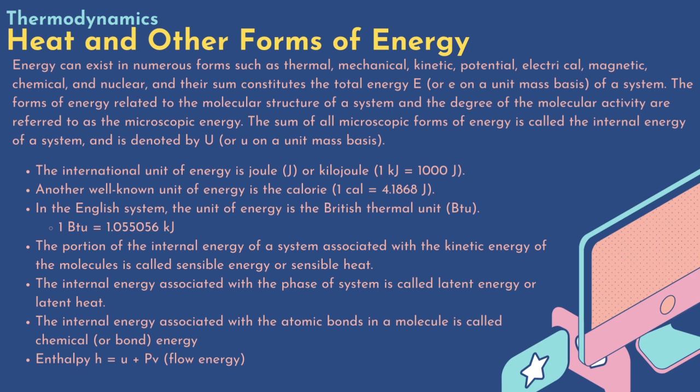In the analysis of systems that involve fluid flow, we frequently encounter a combination of properties, internal energy U and flow energy PV. For the sake of simplicity and convenience, this combination is defined as the specific enthalpy h, or just enthalpy.